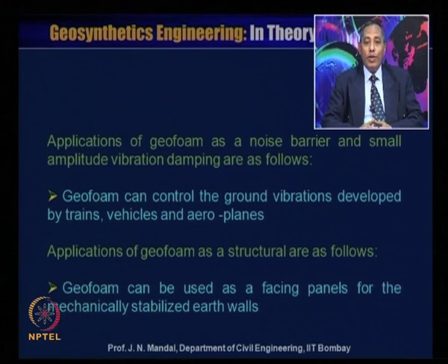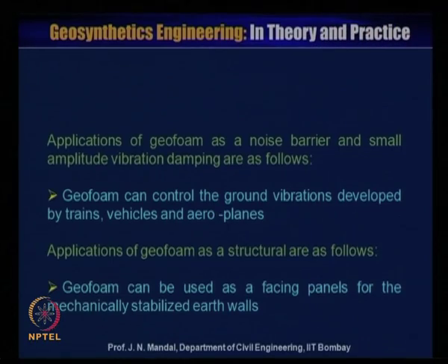Now, application of geofoam as structural is as follows. Geofoam can be used as a facing panel for the mechanically stabilized earth wall. That means geofoam can act as a facing panel itself. So, you can construct the geofoam wall, and some work is also going on in this related area.